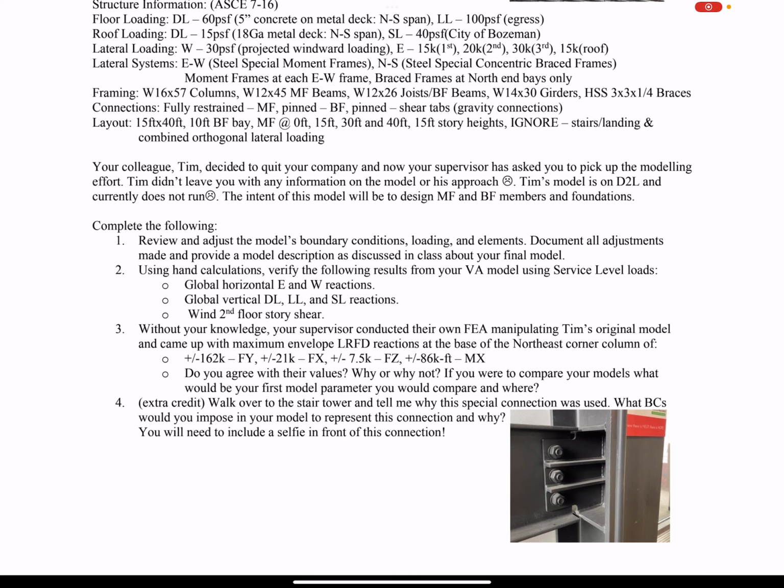How do you offset, like you're talking about offsetting decks? Where is the button for that? And can you do it with areas or does it have to be a plate? Well, you can offset any member. When you click on the actual member itself, you can do an offset and you can drop that member. And you can say, put nodes at top of member, and then it will move that beam so that it's down there. And if you look in the help file, the way that they do that is with rigid links. They end up saying, okay, now I'm going to put a series of vertical...